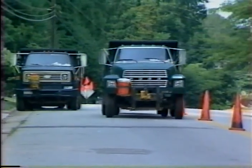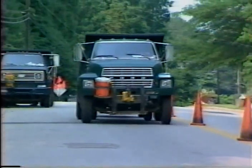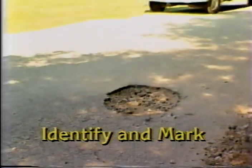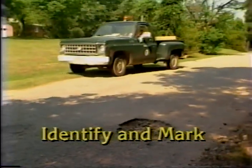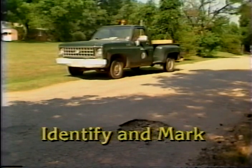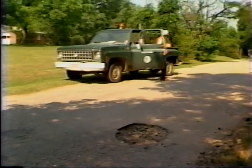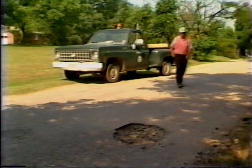With proper traffic control in place, maintenance personnel begin the pothole repair. The first step in the 6-step pothole repair procedure is to identify and mark the areas to be patched. This is best done by a supervisor or crew leader ahead of the patching operation.